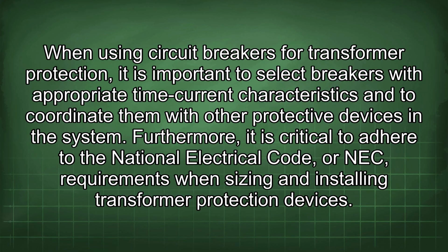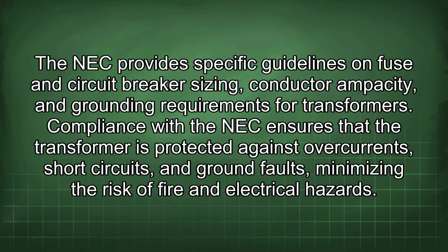Furthermore, it is critical to adhere to the National Electrical Code, or NEC, requirements when sizing and installing transformer protection devices. The NEC provides specific guidelines on fuse and circuit breaker sizing, conductor ampacity, and grounding requirements for transformers. Compliance with the NEC ensures that the transformer is protected against overcurrents, short circuits, and ground faults, minimizing the risk of fire and electrical hazards.